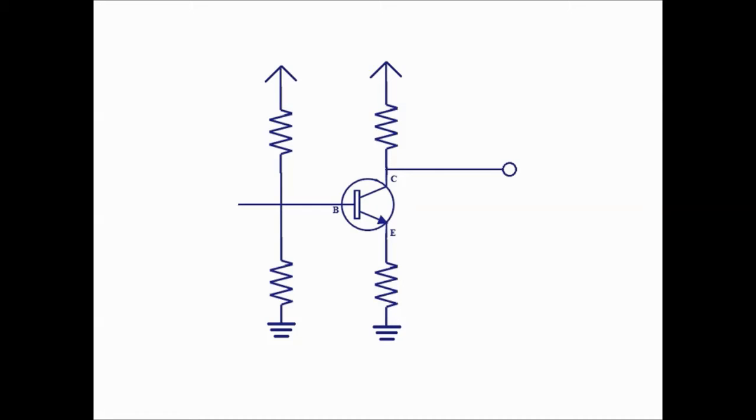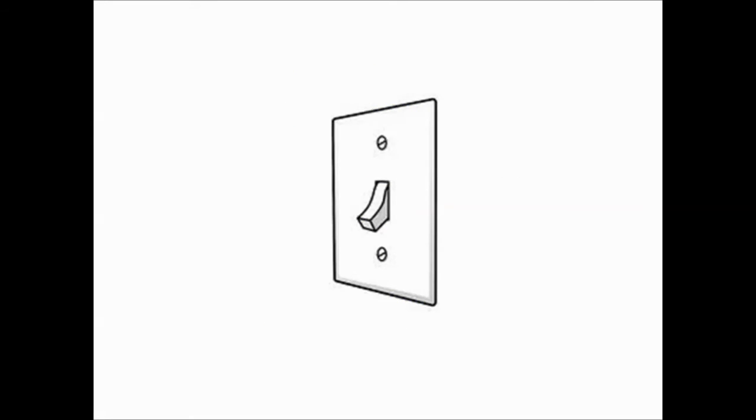One thing you can also do is configure it so that it takes almost not even a turn, just a nudge, and it'll go from 0 to full blast. Nudge it back and it'll go from full blast to 0. In this case, they now call it a switching circuit because the transistor acts like a switch, just going from on to off and on again.